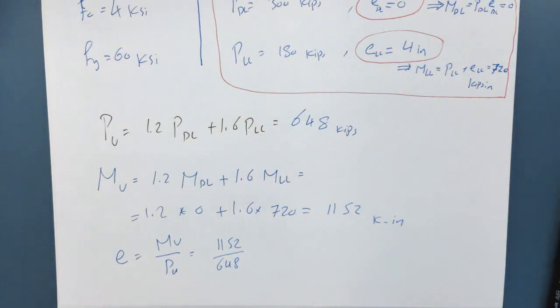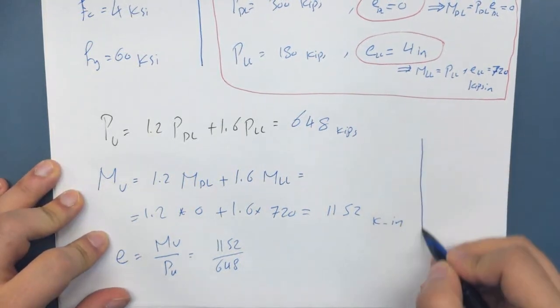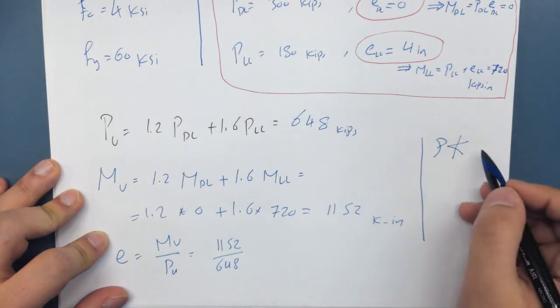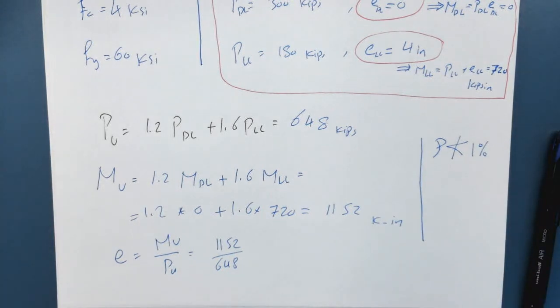One other thing this problem is teaching us is that if you go in, you will see that this node goes inside the last envelope. And the last envelope is 1%. This is the last envelope because at any given section, we cannot go below a reinforcement ratio of 1%. So if you find yourself needing 0.5%, it's not allowed.